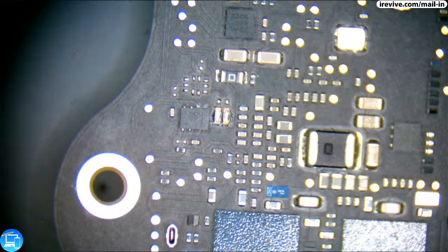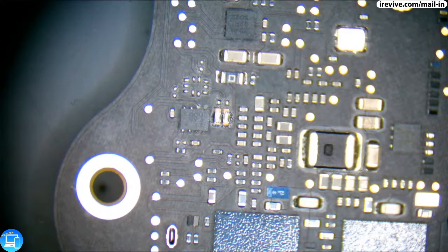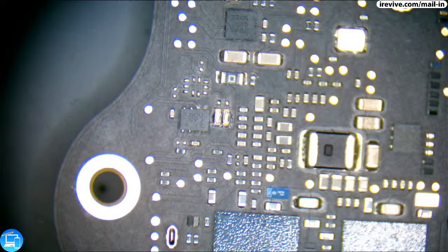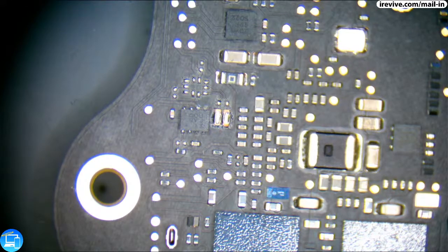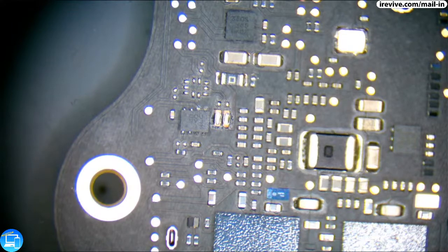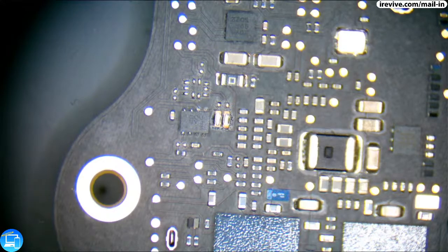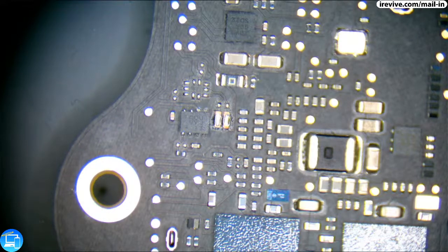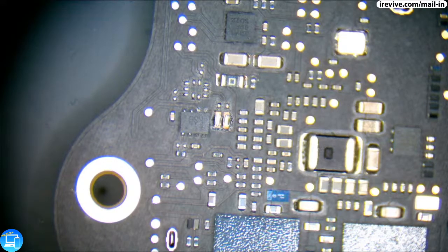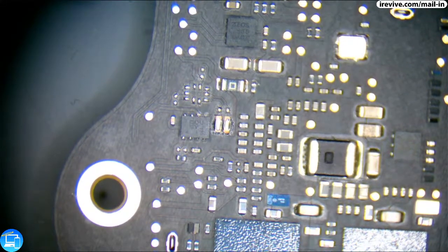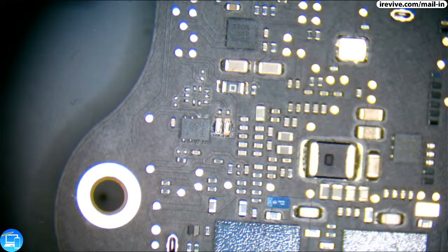We're not getting any voltage, and when it's turned off, we're not shorted to ground, probably because the CD3217 has to actually be on. So let's skip this part. This is just a red herring. Let's keep going. And this is where it starts getting a little bit complicated, because that eventually makes its way to TBT RTD3 power enable, which is part of our POC GPIO. Okay, we are definitely going down a rabbit hole here.